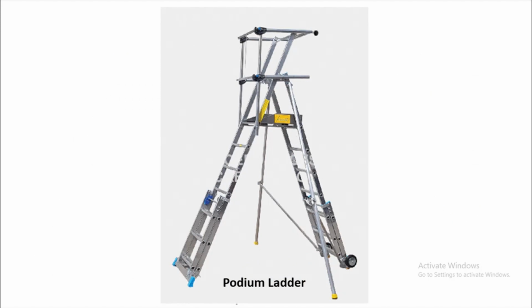Sometimes if you need to do the job a little bit longer, remember, when using the ladder, I would suggest a maximum of 15 minutes of using the ladder, because it's not intended for long and continuous work. Okay, the podium ladder sometimes will give extra safety for you, because there is edge protection and there is a stabilizer on both sides of the step ladder.